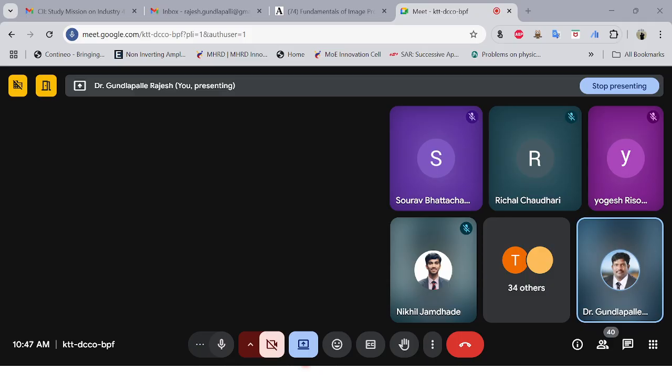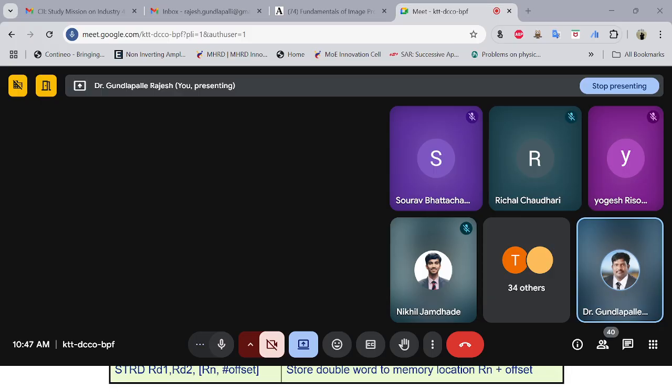Now all these instructions we will do with the help of data transfer instructions. If you want to perform all those operations, we should be aware of these data transfer instructions, which are categorized into four: moving between register and register, moving between memory and register, moving data between special register and register, and moving an immediate data value to a register. Now see here, instead of using move, we can use load and store instructions. The other name of ARM architecture is load store architecture.